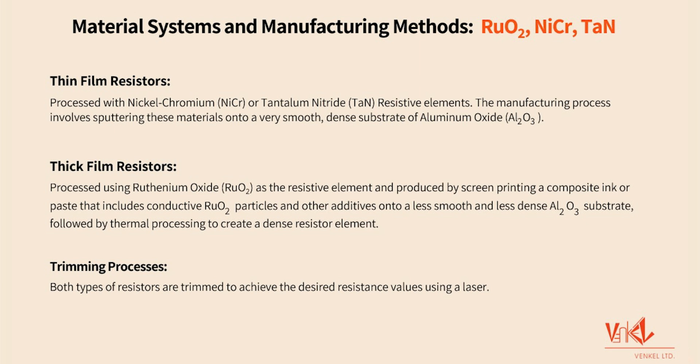To ensure both types meet their specifications, a laser trimming process is used to fine-tune the resistance values. The choice between thick and thin film resistors ultimately depends on balancing performance requirements with cost considerations, allowing engineers to select the best option for their specific application.